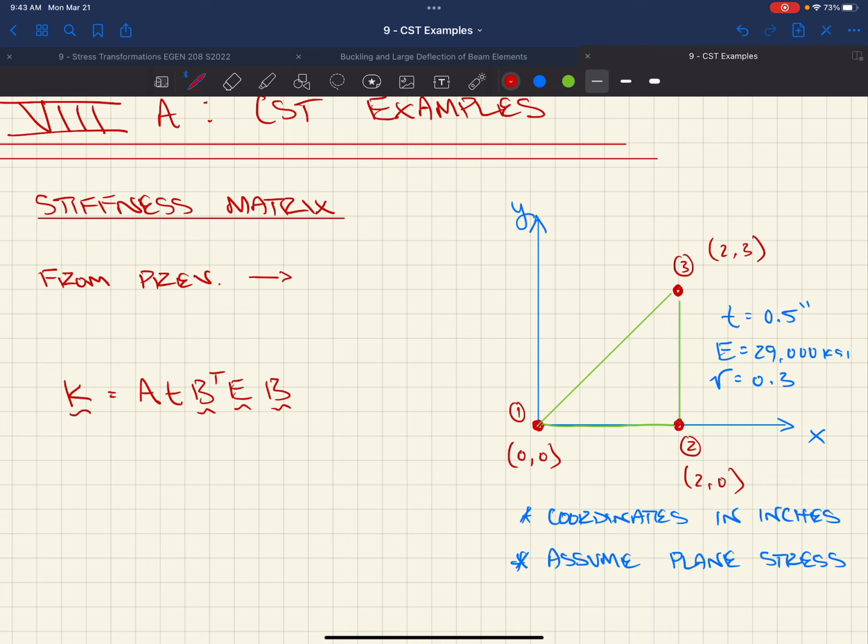It might be a terrible answer. The example Adam showed was of a guy with the nickname Astronaut, because his model deflected 7 light years. You're going to get an answer, but because that stiffness is very, very small, like 0.00000001, and that 1 came from doing multiple operations of this stiffness and not ending up at perfect 0. When you divide 3 by 4 or something like that, it goes on for so long and you don't get an exact answer, and you do that multiple times.